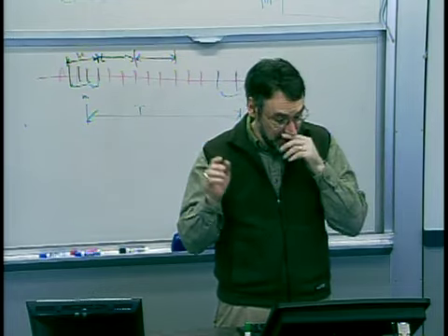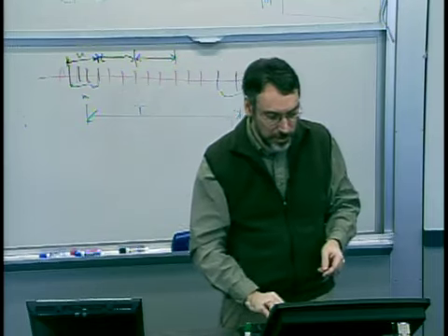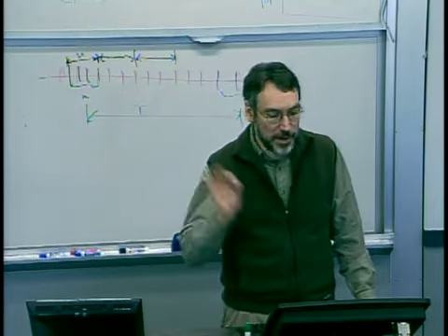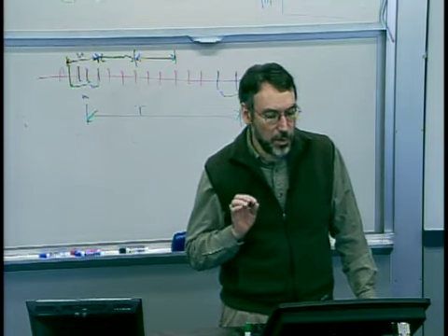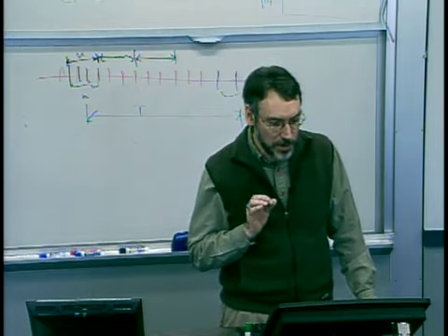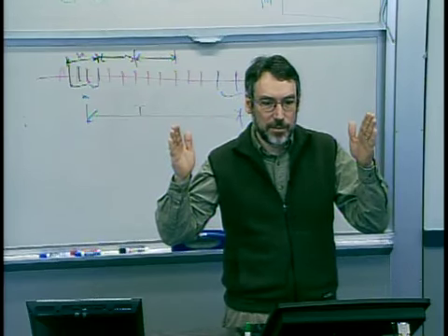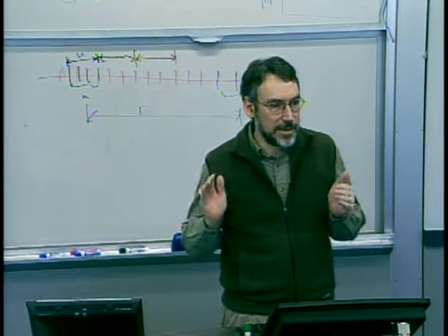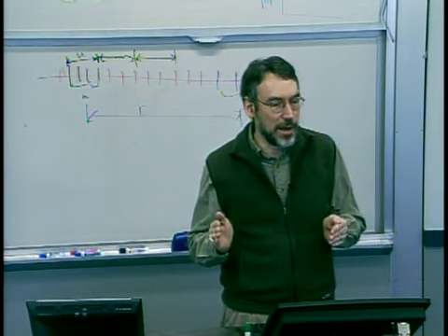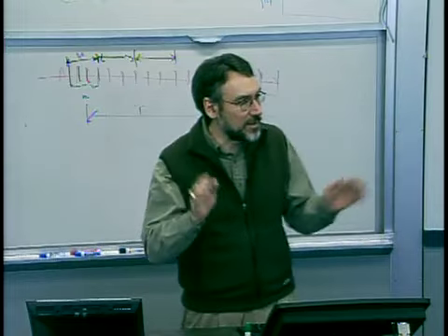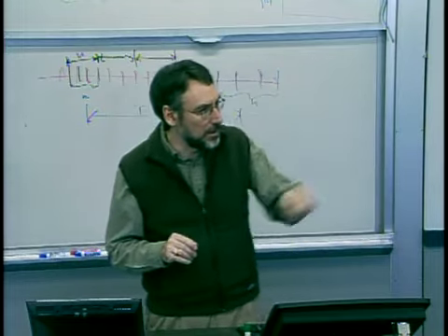And then CPK, as we'll see in a minute, also pulls in the idea of the mean difference. First off, the definition of CP, or process capability ratio, is simply the distance between your upper and lower spec limits and 6 sigma of your underlying process. Now you start to hear the 6 sigma kinds of terminology.